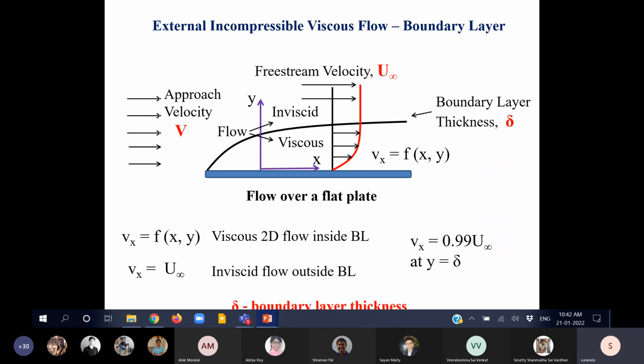The amount of heat generated when a bullet travels through the air due to viscous dissipation, which is something similar to solid friction, can also be attributed to the transport processes taking place inside the thin boundary layer. So the combined study of heat, mass, and momentum transfer together has its origin in the understanding of the boundary layer. So in chemical engineering, we cannot live without a complete and proper understanding of the flow processes inside a boundary layer. And from now, we are going to spend quite some time on this.